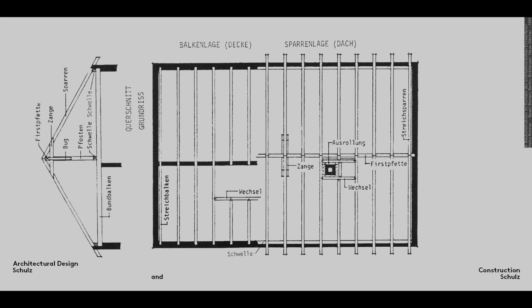It is also important to include design elements such as doors, windows, and staircases, as well as the walls beneath the roof. The walls on the right-hand side of the plan view are incorrectly drawn. They should be shown as top edges. In the cross-section, however, the walls should be shown as cut edges, and you should indicate the rafters and beams in the plan view. Cut wooden members are indicated by means of a cross.